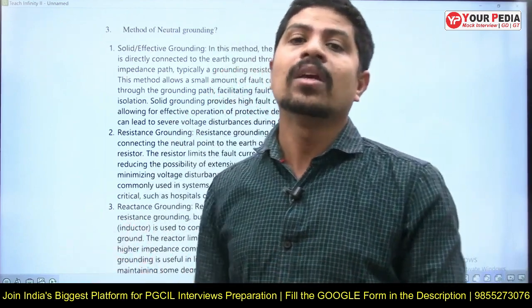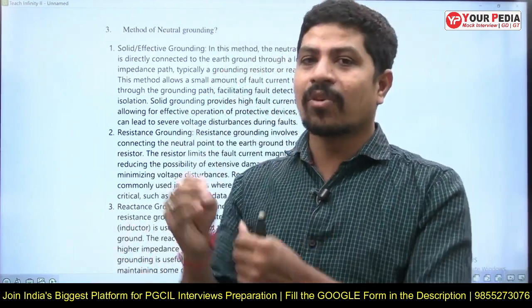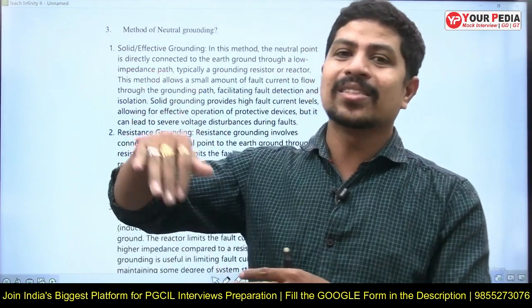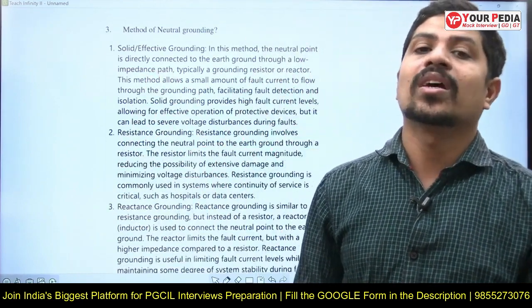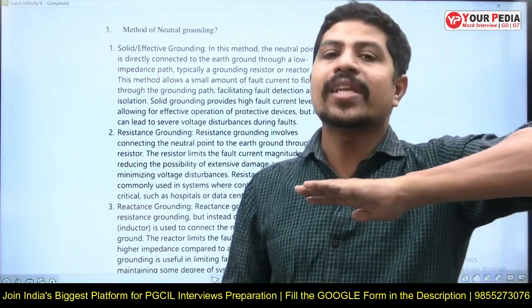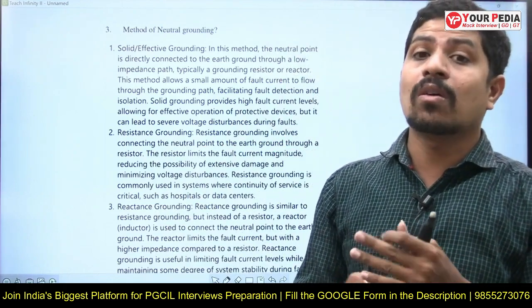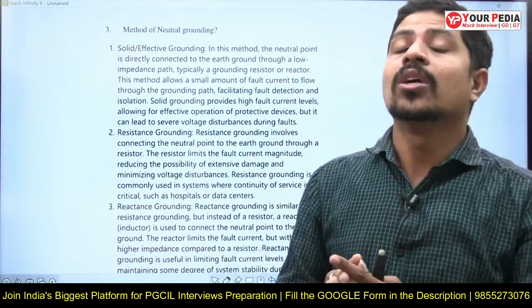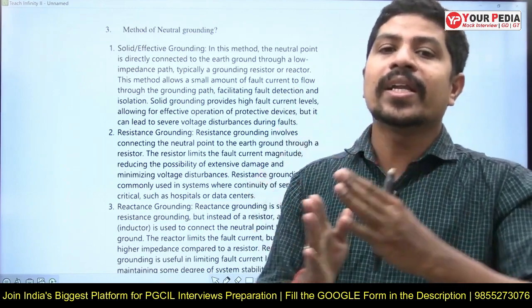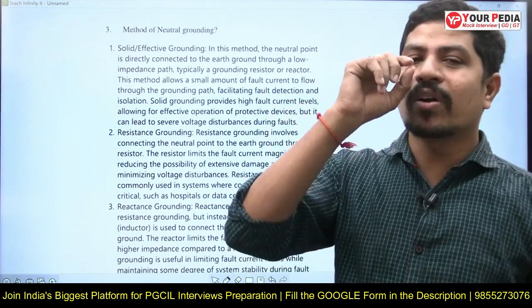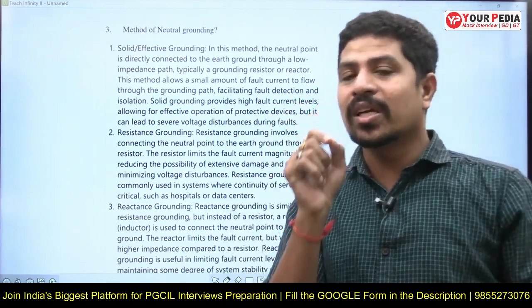Therefore the fault will remain, because of which some fault current flows through the capacitances of the transmission line, due to which the phase voltage will rise to line voltage. This concept is called arcing grounds. Due to this, voltage will increase and insulation will be damaged. Therefore definitely the neutral of the generator has to be grounded. Now, all the types of grounding.